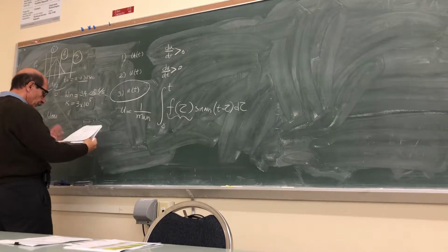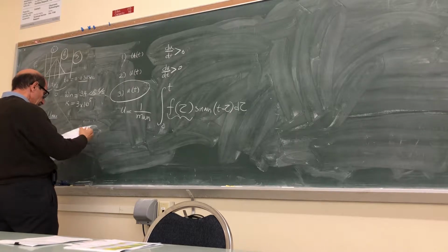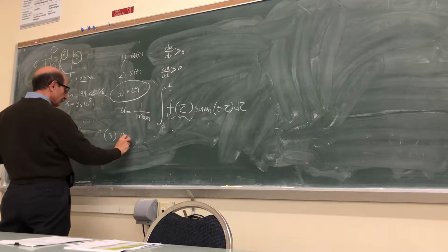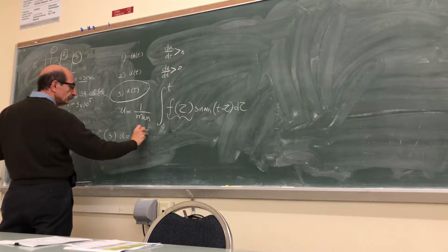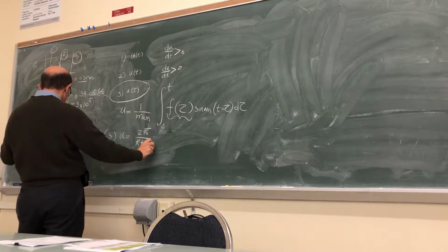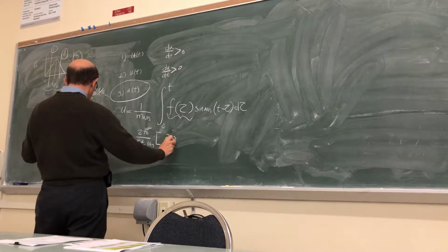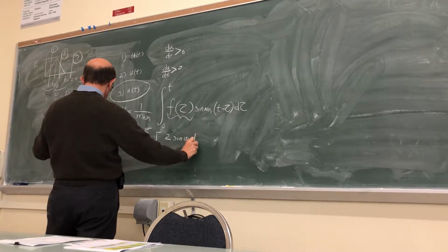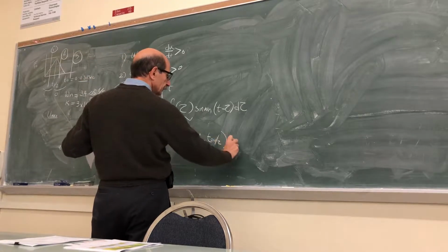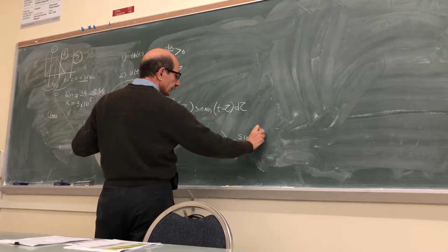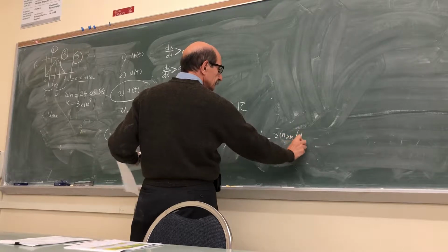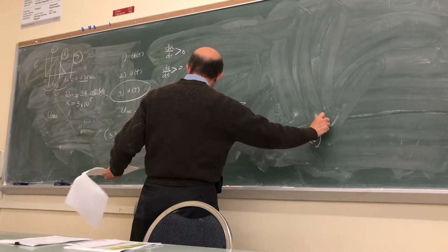displacement function, as we had derived, for region 3 was 2f naught over k t0 omega n times 2 sine omega n (t minus t0 over 2) minus sine omega n t minus sine omega n (t minus t naught), right?